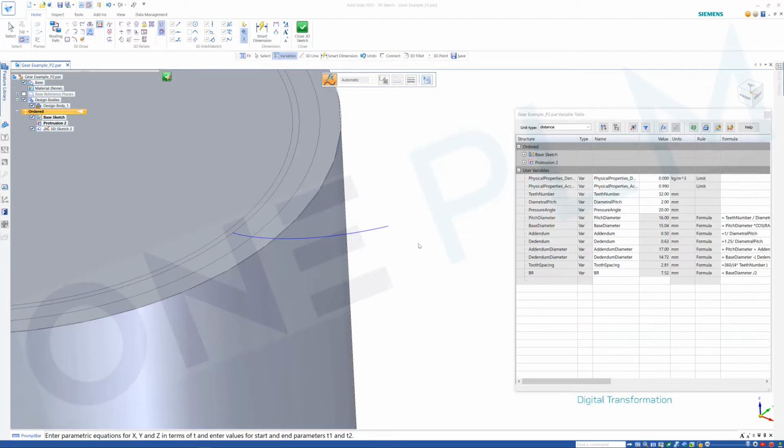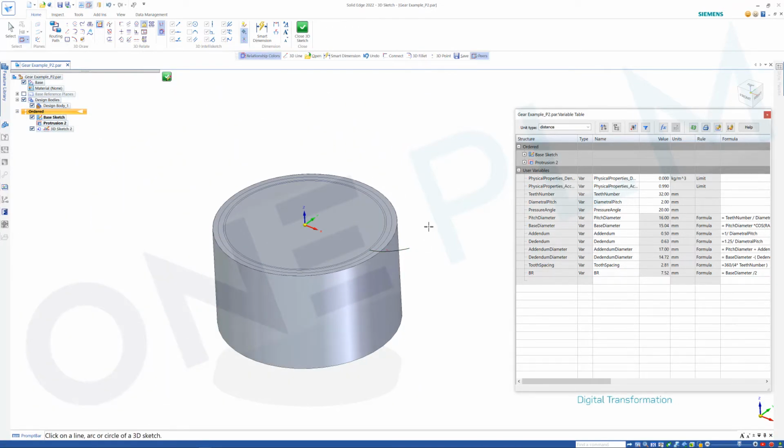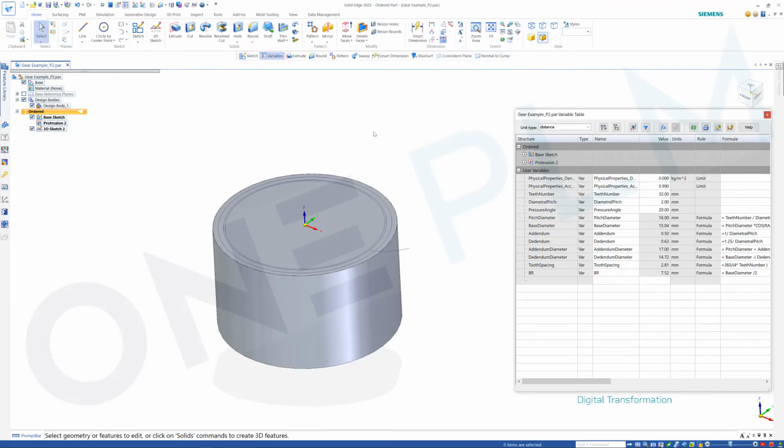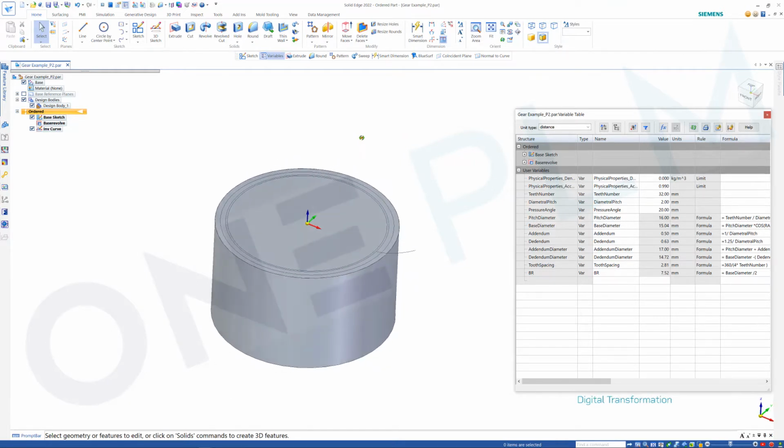We can then click OK. Just to make sure this works correctly, I'm also going to choose the little lock icon and click on the line that we've just created so it goes black. If we haven't got our relationship colors on, we can turn those on up here. We can then close that. I'm just going to change that to involute curve, and I'm going to change that to base revolve on there. Just makes it easier if we're going back to something else now.